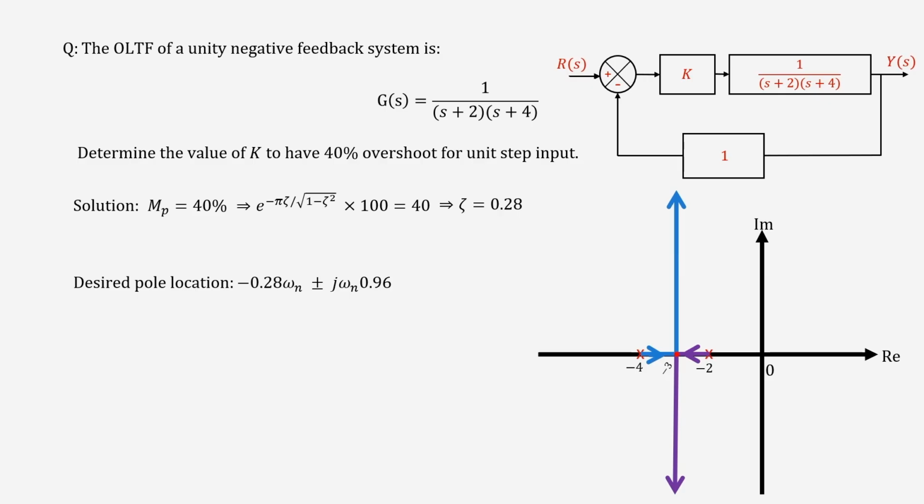On MATLAB you can directly find the root locus using the command rlocus. Use rlocus, and within the brackets give the transfer function, and you will get the root locus. Of course, you can draw it directly from MATLAB, but you should understand what it means. So, better you first go ahead with all the points that are given to you and try to draw the root locus on your own; you will get the intuition.